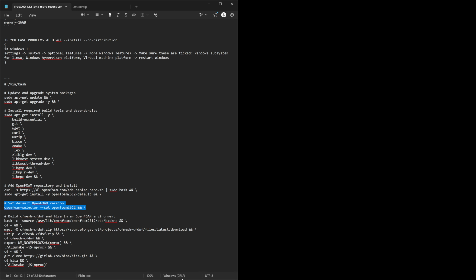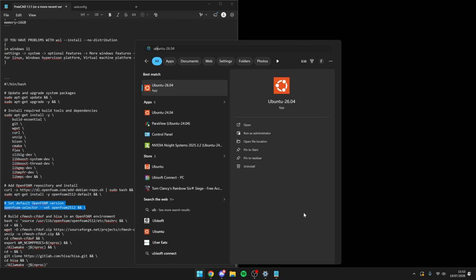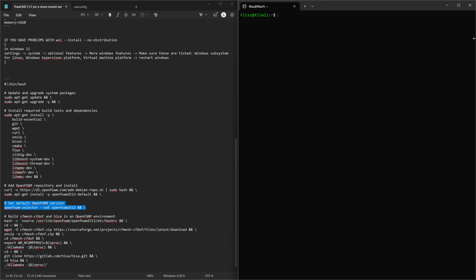Great. So I did it before, so I'm not going to wait for it anymore. But after that, you press ls. This tells you all the files. And now you can check what's inside of OpenFOAM. You press cd for change directory, and then OpenFOAM, and then press tab once. Press ls. You can see that this is the OpenFOAM version, and there are files inside of it.